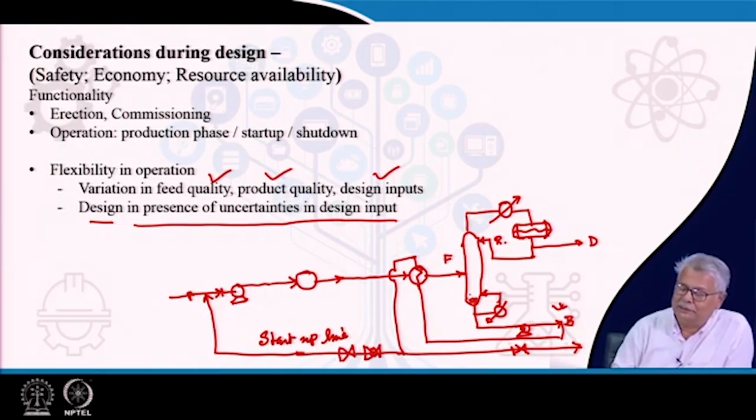So, what happens is with time, since it circulates through the reboiler, which has to be kept on, its temperature goes up, the vapor starts forming, it goes up the cold column, condenses in the walls and the trays of the cold column and starts coming back.